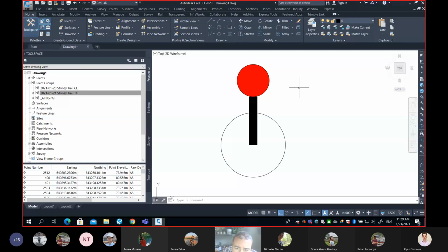Everyone is clear? So if it doesn't exist, use your CAD tools to draw this thing. If you have downloaded it from the internet or it's part of your company library, then bring it in. The next step, after you draw it, bring it in or download it, doesn't matter, is to turn this into a block. Step number 2, which you must do: turn it into a block.